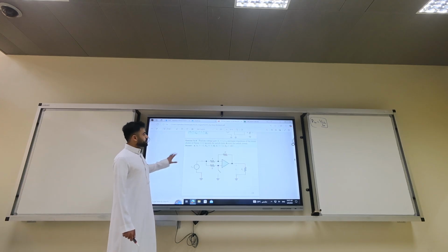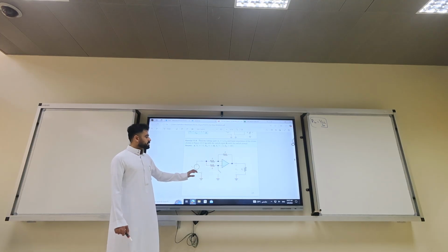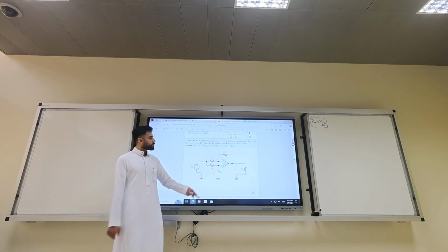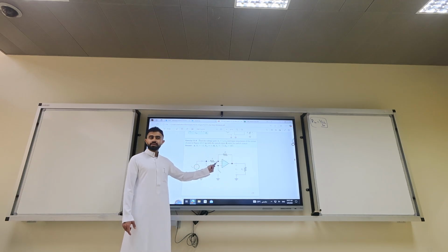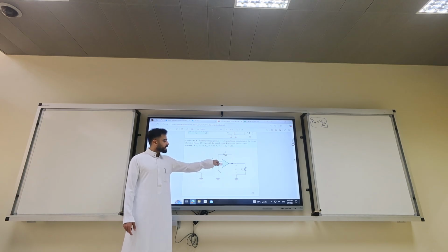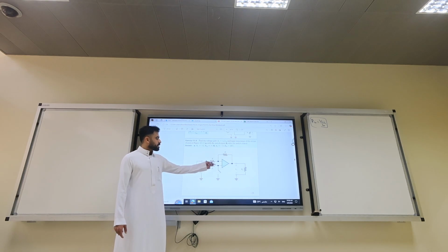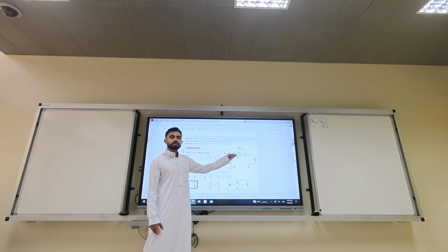We also talked about this example, and we said we will start with the closed circuit. This one is an interesting example because the input is fed to the positive terminal and is fed to the negative terminal. So it's kind of a hybrid problem. And then you got a switch here. But also we verified the existence of a negative feedback. Because we have a negative feedback, V negative equals V positive, or we call it Vx, the voltage drop is zero. Now when you close the switch, here we have a ground. This implies that we have a virtual ground here.